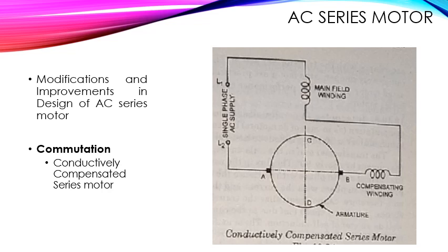The fourth one is, the increase in armature conductors causes an increase in the inductive reactance of the armature, and thus there is no reduction in the net reactance of the machine. So in order to overcome this difficulty, the machine is provided with a compensating winding which neutralizes the armature MMF.